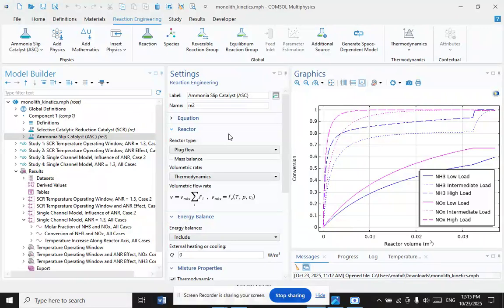And the general aspects. Synthesis of monoliths is usually carried out by agglomeration of molecular subunits via cluster formation mechanism using unreactive porogens to create size control domains where mass transfer occurs as well as large pores to assure the solution flow through the bed. The process involves formation and growth of nuclei which will interact continuously in the mold to produce the monolith structure.